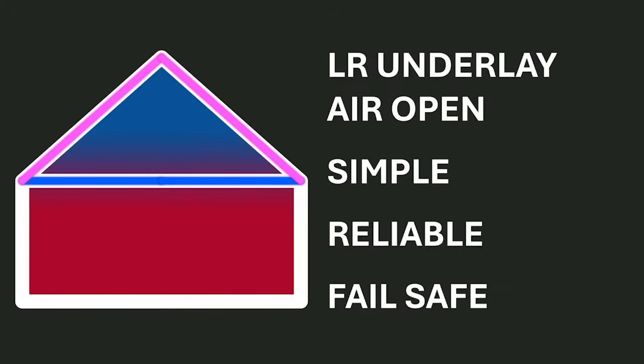The Construction Design and Management Regulations 2015 set out the duties placed on designers, and these must be referenced by both the architect specifying the system and the product manufacturer and installer who are designing the system. Responsibilities include the duty to eliminate, reduce, or control foreseeable health and safety risks through the design process, such as those that may arise during construction work or in maintaining and using the building once built.